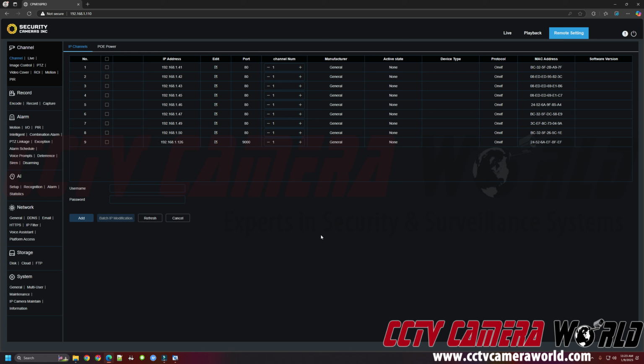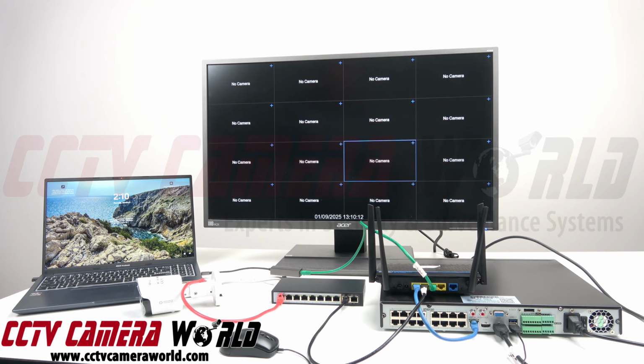In the next portion of this video, I'll show you how to do this process using the NVR with an HDMI monitor or HD television. In the last video, we showed you how to use a laptop to set the IP address on your PoE IP camera from CCTV Camera World. Now what I'll be doing is taking the laptop away.